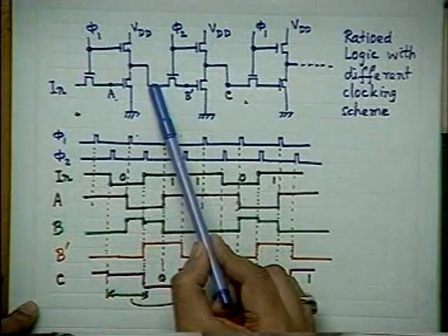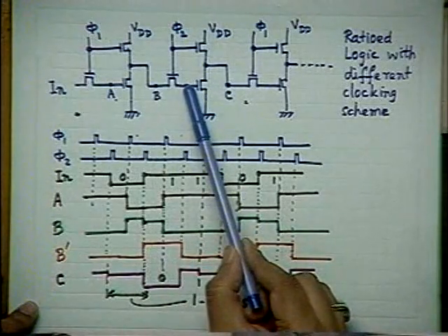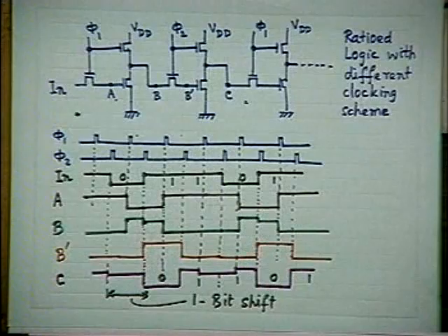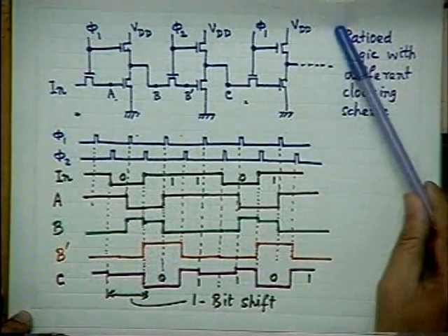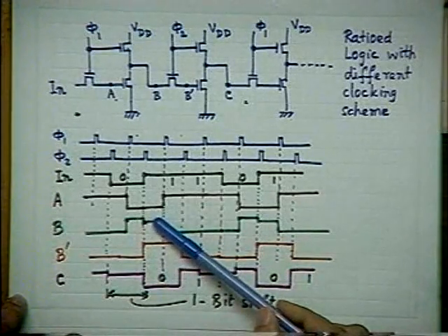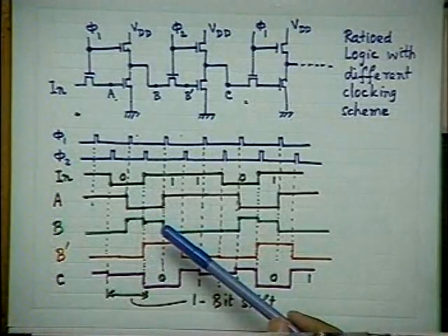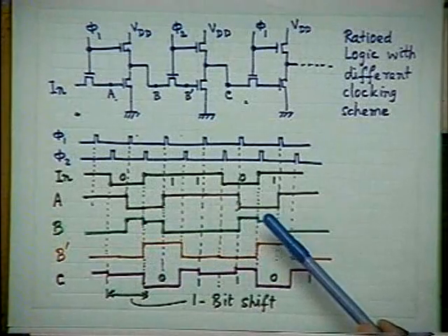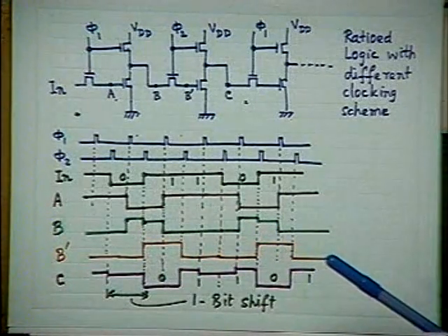And as a result, it is not unusual to maintain the condition that the capacitance at the node B is large compared to the capacitance at the node B dash. It is more or less automatically satisfied because of the ratioed logic which we have used to implement this circuit. But please remember, there will be some fall. Our design methodology should be such that these kinks are minimized. That means this kink must not fall below what? The unity gain point, that means below the noise margin of the high state. Okay? So that has to be kept.